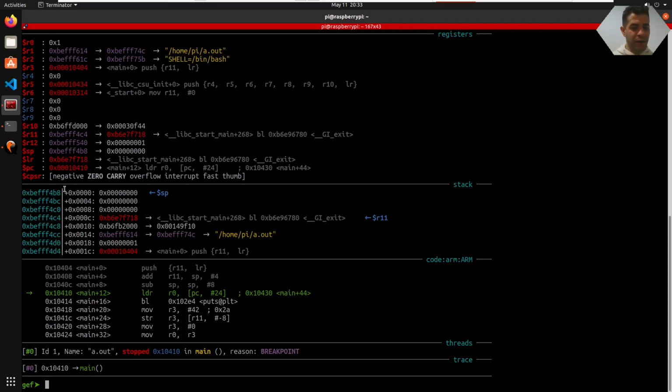Oh, for example, another thing that I see here, if you have a look at the last thing that we already discussed, we were talking about the CPSR, and here you see we have set the zero and the carry flag. Okay, so when you see here some uppercase name, it means that the bit here is set, otherwise no.